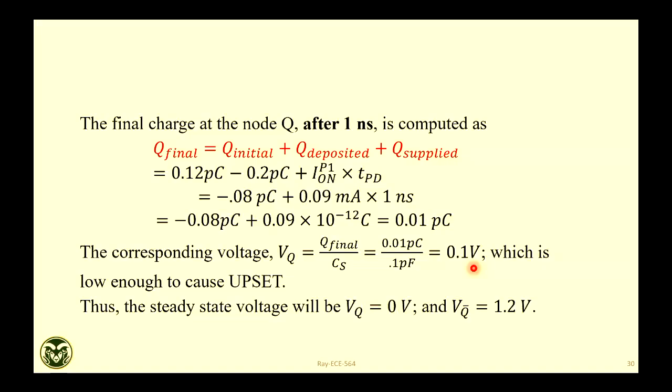Any more questions? Those are important, right? If you think about it from a system engineer's view, now you have to do this dynamically. What hold voltage do you want to go to? These are the critical criteria, because during hold condition, if a bit got upset, you never noticed. This is called silent data corruption. Suddenly you'll see data doesn't make sense, or your SRAM FPGA is having a different configuration file. So yeah, those are critical for understanding soft error.